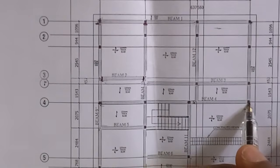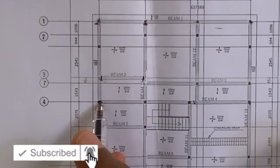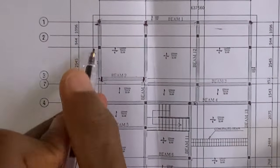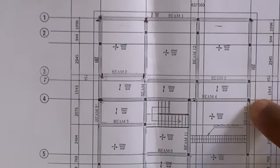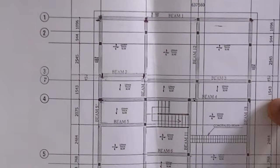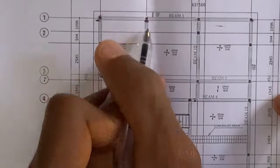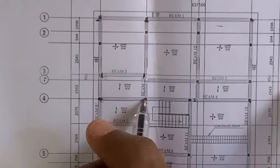Once we get the center to center dimension, we will now minus what? Half of the thickness of this column, and half of the thickness of this column, because it is intersecting beam 9 and beam 13, which we've already calculated. Now remember that we've measured for beam 10A, and this beam 4 is cutting through beam 10A. So we have to minus this point of intersection, which is the thickness of this column.